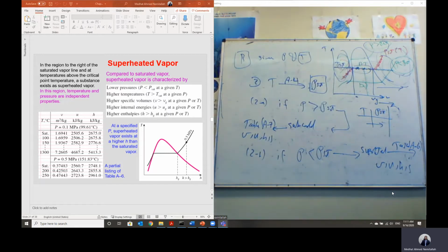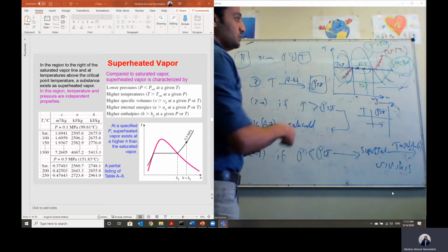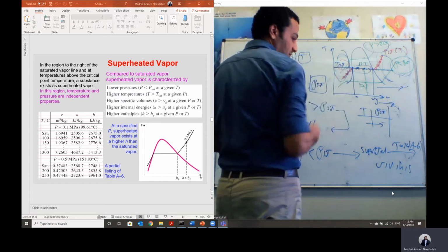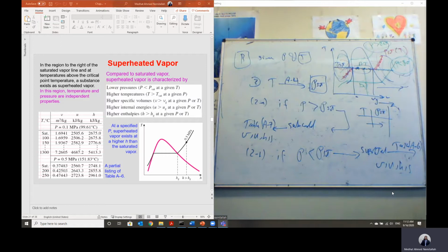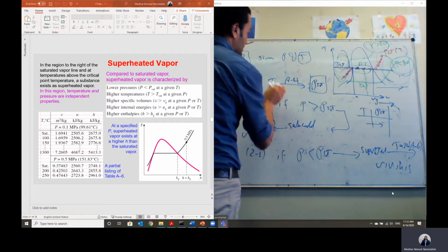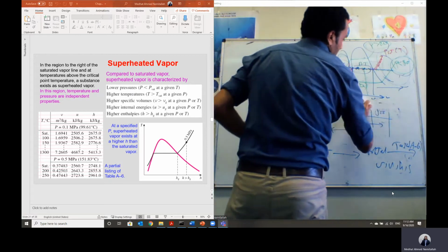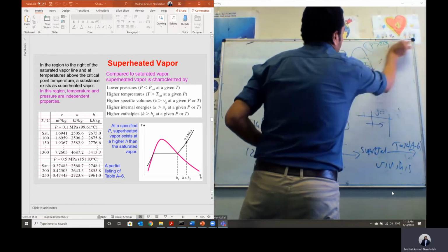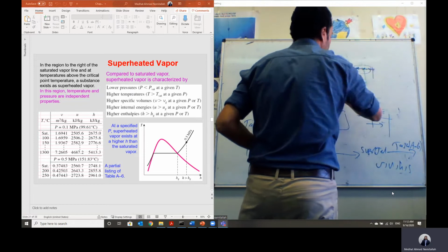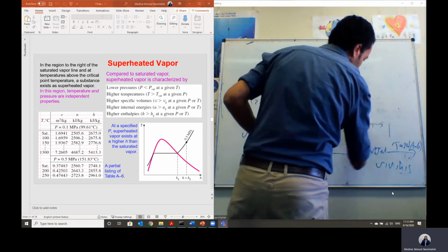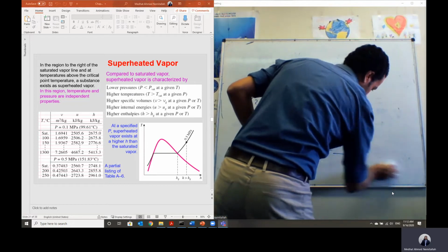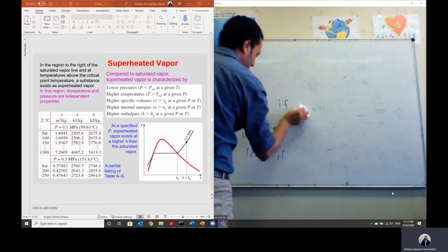Okay? So given either pressure or temperature with one specific property, we can follow step A. Or, if pressure and temperature are given, we said they are not independent in the saturated zone. Then the state will be either subcooled or superheated in this case. Okay. So let's have a third option, which is also very important. It's a kind of special case.